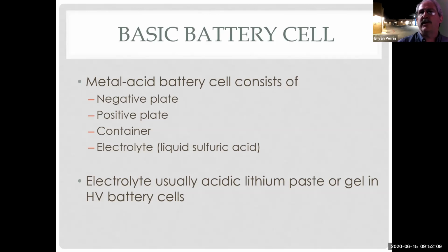Batteries for automobiles are sold what's called wet. That's where they already have the electrolyte in the battery when you buy it. If I buy a motorcycle battery or some other special use batteries, they come what's called dry. That's where the battery acid is in a powder, and I would mix that with distilled water and actually set the battery up and balance it using a hydrometer. We really don't do that in the field anymore. Hazardous waste is part of it. If I buy a motorcycle battery from Interstate, even though they store them dry, they're going to fill it up, charge it, set it, balance it before it ever comes out to me.